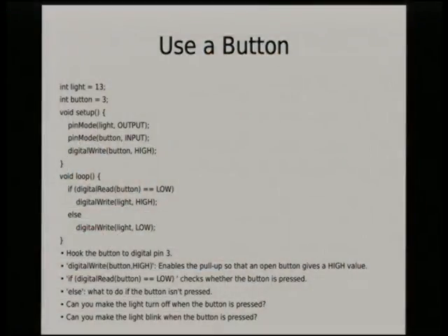So we talked about the buttons we have, which are just switches. They're not switches with a resistor, they're just switches. So in order to get the button to work at all, I had to go through usually about 15 minutes of talking about a pull-up resistor. And that was a mystifying notion. Why would you need a pull-up resistor in this environment?